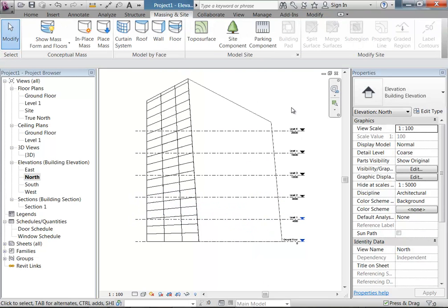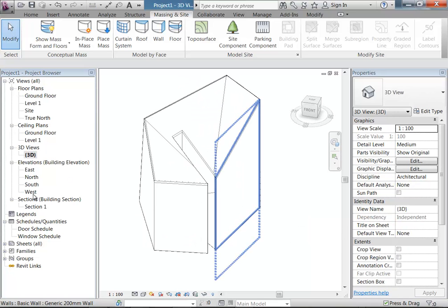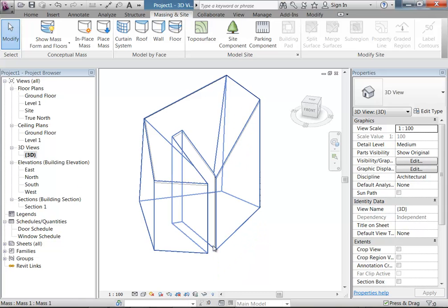Okay, so I've got some extra levels there. Now I can go back to 3D. Wait, so how did you array and then what did you do? Did you create those levels and then array? I just use the array tool, yeah. I've turned off group and associate so they don't come up grouped together afterwards. So you just have a go with that.